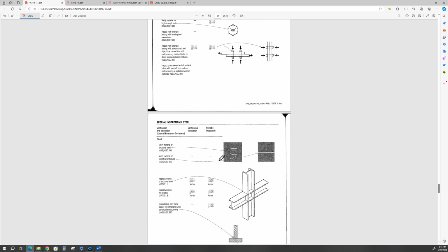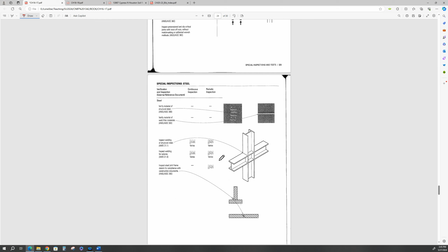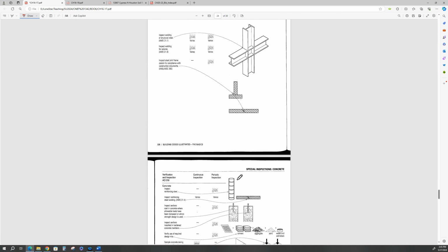That's pretty much the salient issues for Chapter 17. Now, this is a welded up frame. The World Trade Center was welded bundled steel where they would run what? 3 floors? 4 floors, 3 floors at a time of structural steel. So these welds can be visually inspected or they can be radiographed. That's all in the specifications in the code. They specify the filler metal that's being used, whether it's the E6011, E70, E70 series. That's under the welding specifications, the welding process.